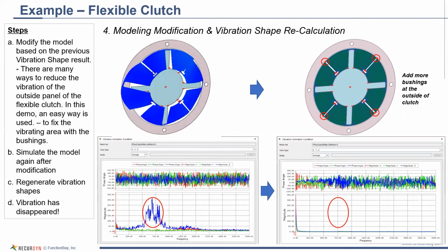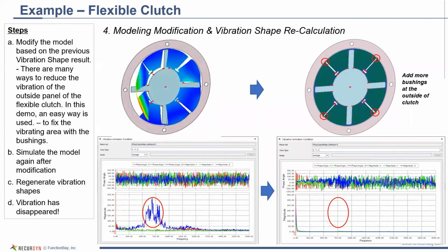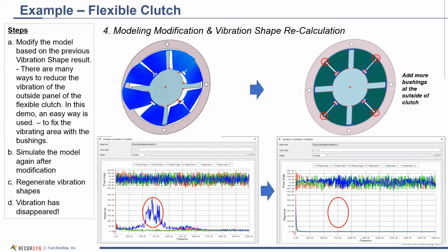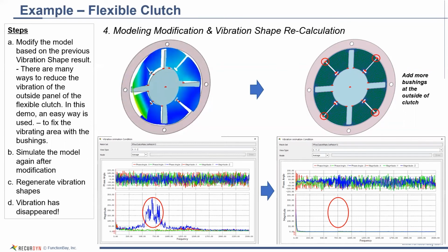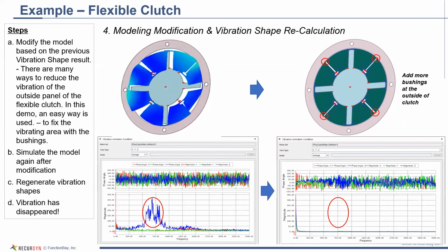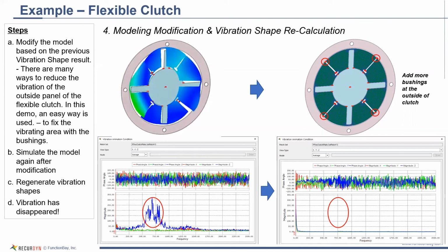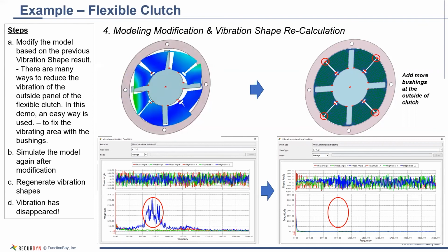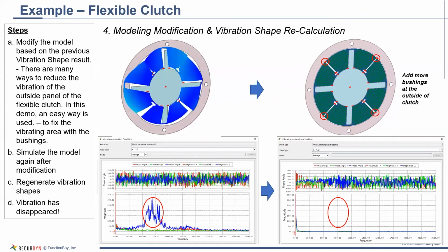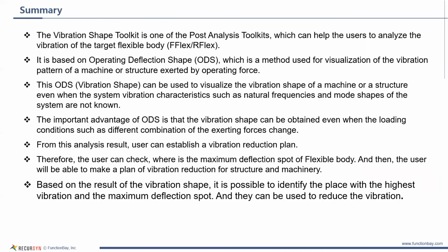Understand vibrations as expressed in the time domain. One of the things this avoids is that if you have different mode shapes, different modal frequencies, from a modal analysis, it's maybe hard to focus on which mode shapes need to be dealt with. And with this method, you can look at the mode shapes that have the high magnitudes and then address those modes, as compared to trying to address all the different vibrational modes, and maybe some of them are not being excited anyway. So this helps you see that.